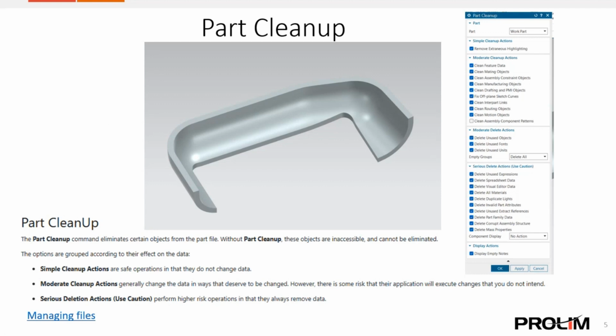If you know this part is used in several areas, if it's used in a drawing, an assembly, or if it's used downstream, make these changes with the revised part and make sure that nothing's changed that you don't want to change. So you've got to watch it when you use part cleanup. Now, myself, I've used part cleanup on a lot of parts that are very complex surfacing.